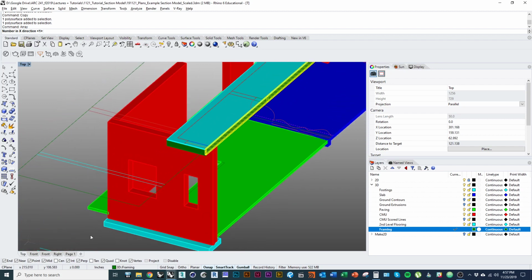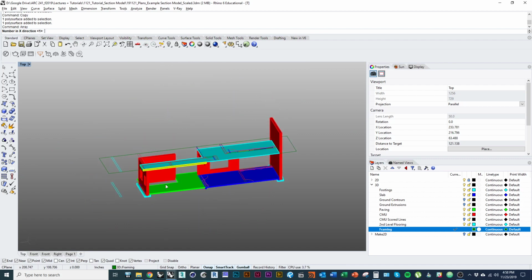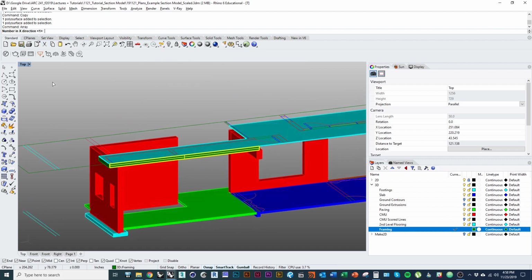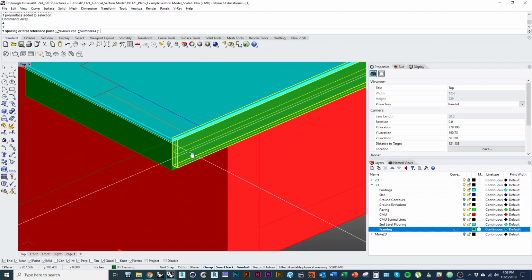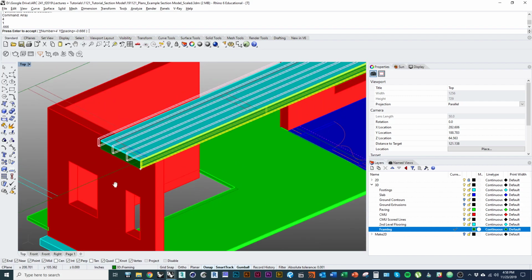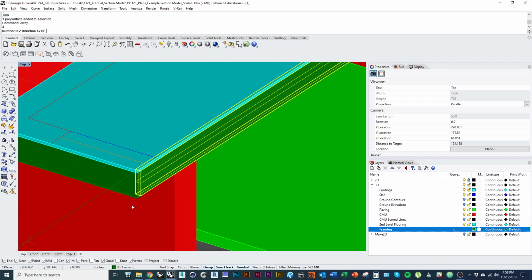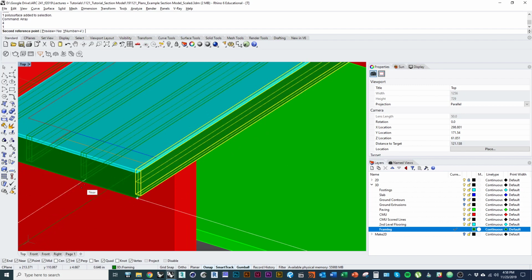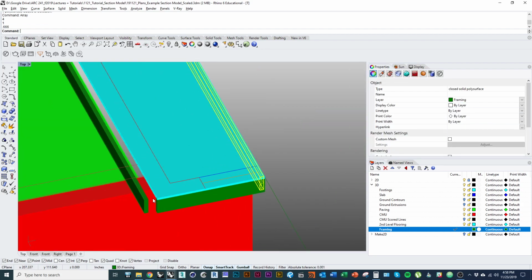But okay, so let me then copy this geometry a few times. Again, I'm going to use the command array. I want to array it in the y direction. So for x I'll leave that set to 0. For the y direction I'll do like 3 or maybe 4, I'm not sure exactly. For the z direction I'll set it to 1. And then just like before, I'm going to use the dimension 16 inches, or 0.666. Alright, and then click. I messed up. So 1, 4, 1, start point, 0.666, enter, and then click, and then right click, or press enter.